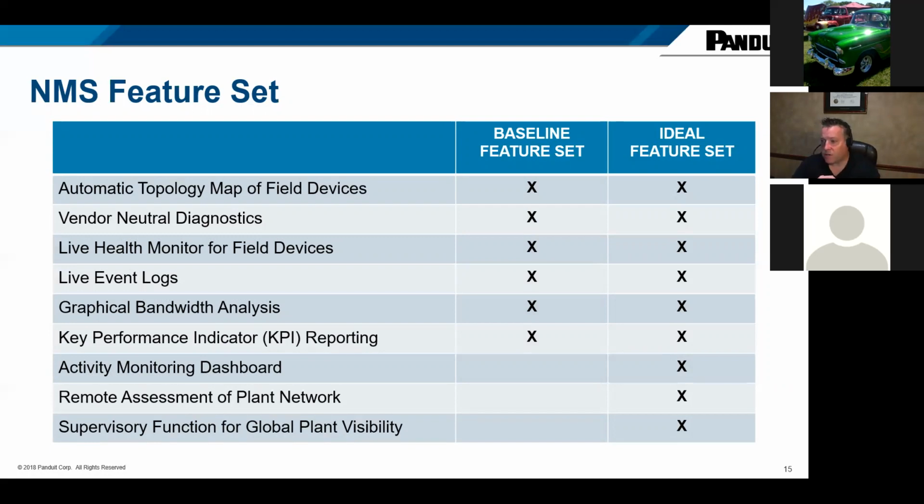Live health monitoring for the field devices. It goes all the way to the edge. It logs everything, and all these software packages do this, by the way. You can get an event log. One of the things we do with ours, we tell people that buy the Panduit version, every morning, hit the button, print out the event log, and give it to your maintenance guy, and it'll rate the top 5 issues that we're seeing in the last 30 days for the network.